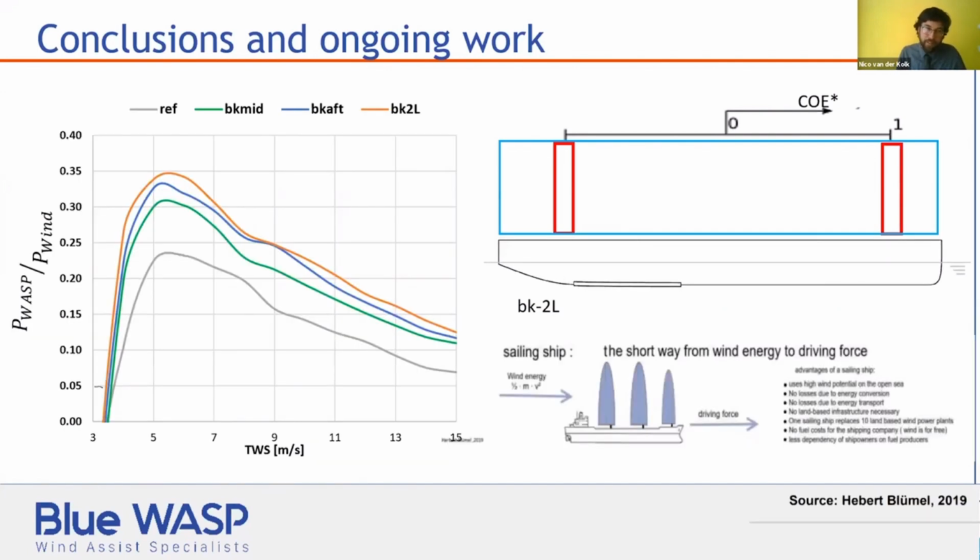Looking at the results again in a graphical sense, I would make one more comment about the true wind speed versus the apparent wind speed. So in our case, the ship was moving, I think, 7.2 meters per second. And in fact, you can observe that the slope of this curve tends to change around this location. So the ship, in effect, when you look at the data this way, receives a boost so long as the ship speed is greater than the wind speed. That's this effect of the apparent wind.